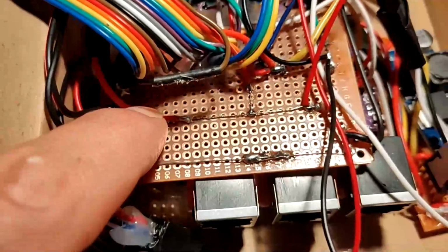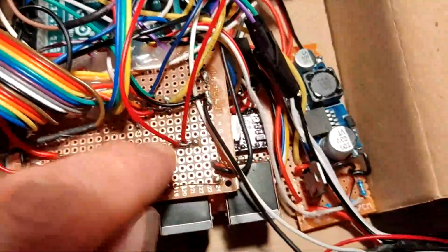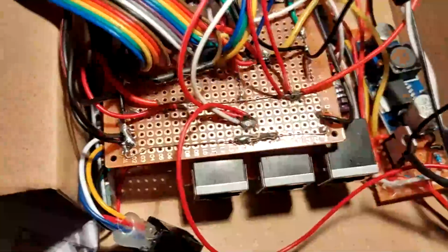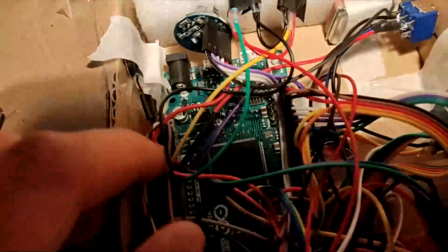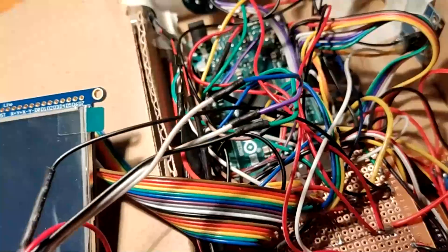Here I soldered the wire for the Bluetooth module. Here you have the wire coming from the RTC module. The 5 volts buck here is soldered on the side. Here these are the 3 wires for the 5 volts Arduino. The wire coming from the GPS. Here you have the wire going to the board, to the 5 volts output, and this is the wire for the joystick. I also soldered the ground and I extended the wires because they were a little bit short.